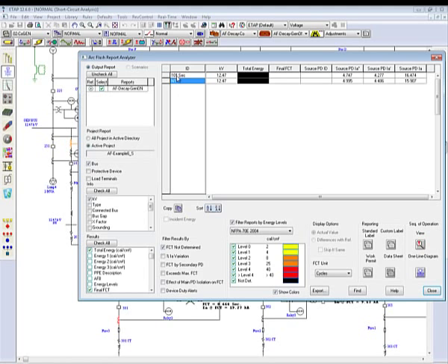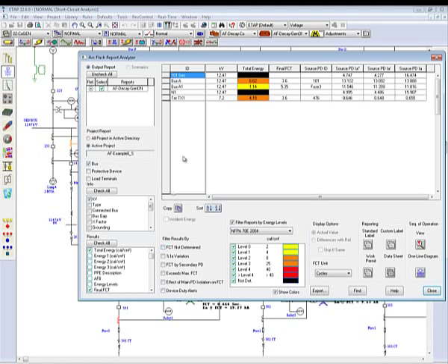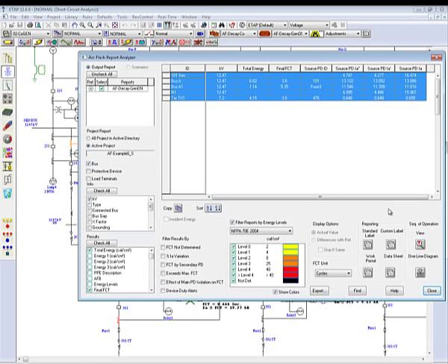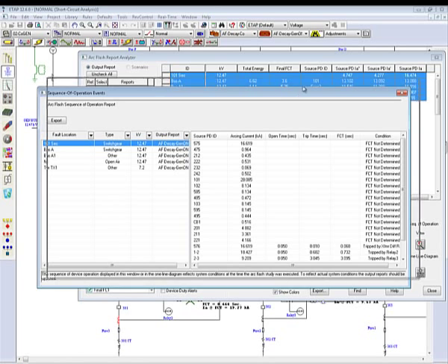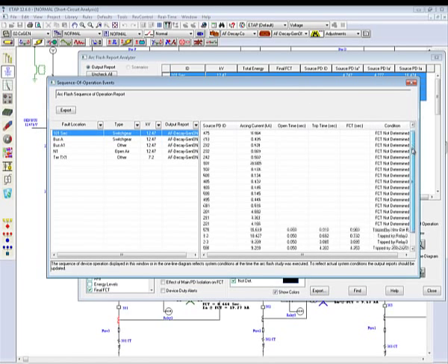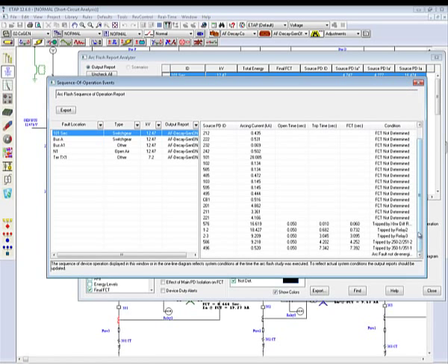You can grab as many buses as you wish by simply clicking on the first row, shift, and the final row, and enabling the ArcFlash viewer and simply launching it. This here will provide to you the full sequence of events and give you the final condition. So for 101 secondary on this switch gear, you see here that the arc fault will not de-energize.